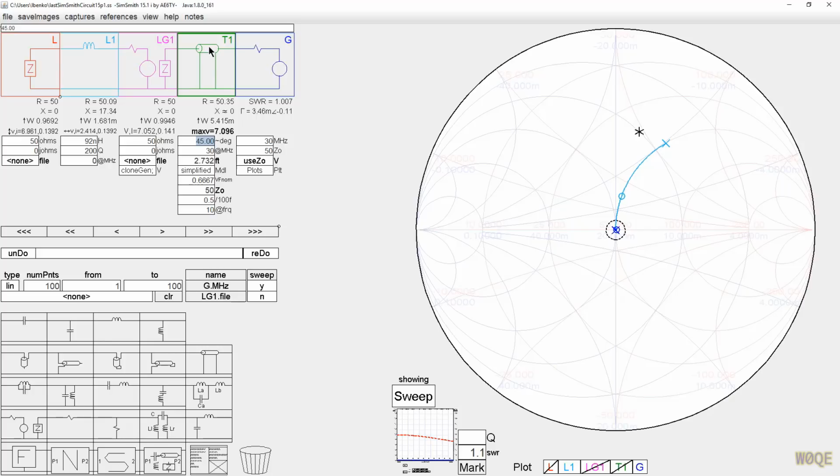And let's see if we can make a transformer here be the same. Let me get this set up. This was a piece of wire. It was 4 inches long, so it'd be a transmission line. It's going to be an air core transmission line, so it's got a velocity factor of about 0.95. It probably does not have much loss at all. It's 0.33 feet long since it's 4 inches.